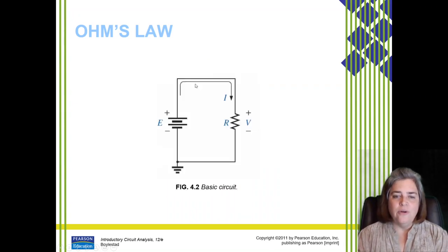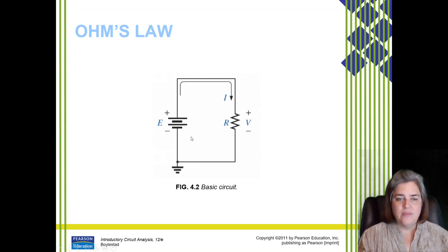So what are we saying? Here is our basic circuit. Here's the voltage supply you learned about last week. Here's the resistor you learned about before that. And then when we connect the positive terminal of the voltage supply to the resistor, and then the negative of the voltage supply to the other end of the resistor, and we have it grounded in our circuit, this gives our current a path to flow through the circuit. So this E, this electromotive force, is what kicks everything off and starts the process. And since we have a complete circuit, we're going to have current flow through the circuit.